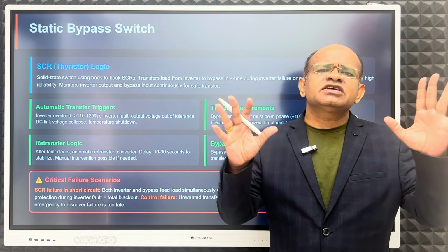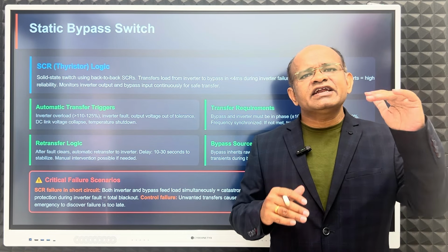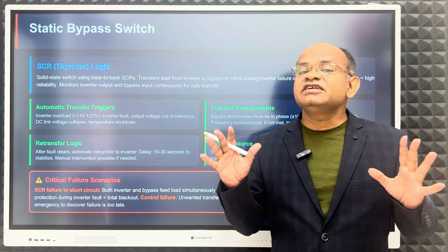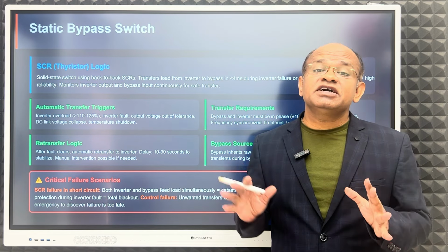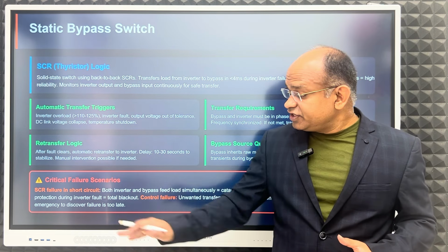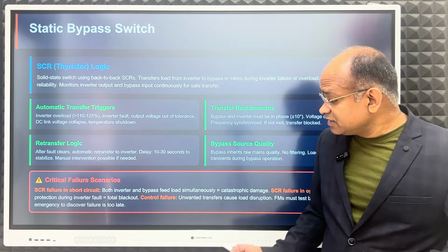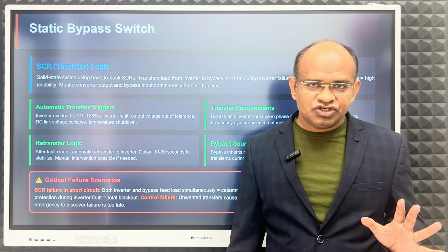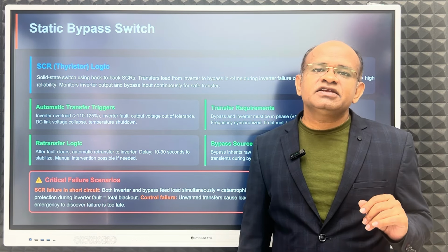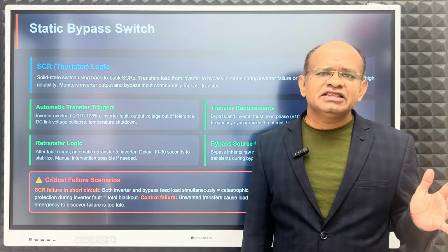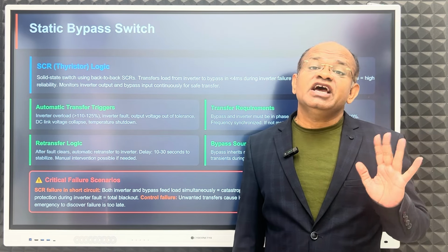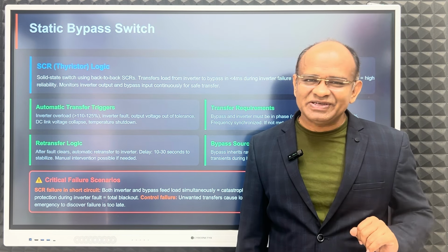Now very sophisticated software is available that will directly tell you whether your static switch is healthy or if there is any problem. DC bus temperature is also another indicator for the UPS. Monthly checking is advised, but check with your UPS vendor whenever he is doing online maintenance, whether quarterly or bi-monthly, if he is checking the health of your STS, static transfer switches.